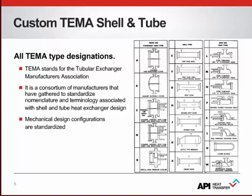The W rear head is similar to the P, but a bit more cost-effective because of the simpler floating head design, where packing is used on both sides. However, this limits its use to low-pressure, non-aggressive fluids on both sides. It is also limited to one or two passes because of the rear pass rib design.